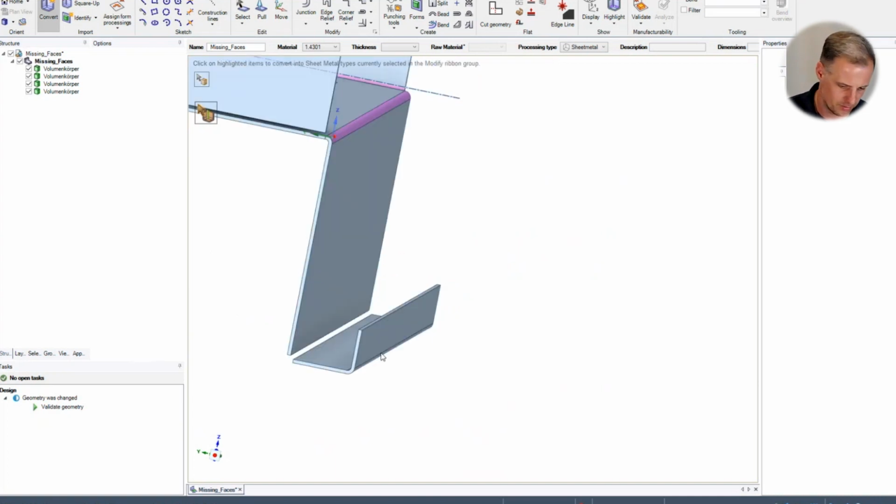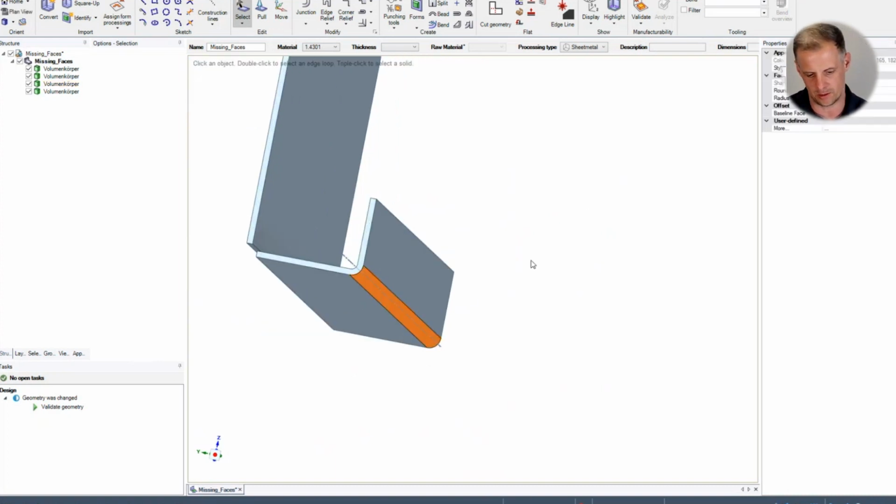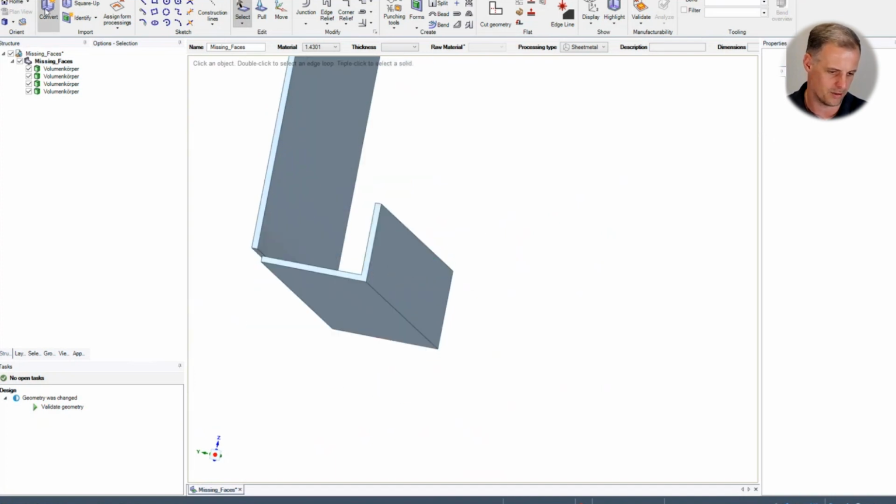Then once again, I can use the select tool, click on the bending, hit the delete key on my keyboard, and by using the convert functionality again and the correct junction, in this case it's a bend, I can click on this red line and convert the sharp edge into a bend. Or let's go back really quick.